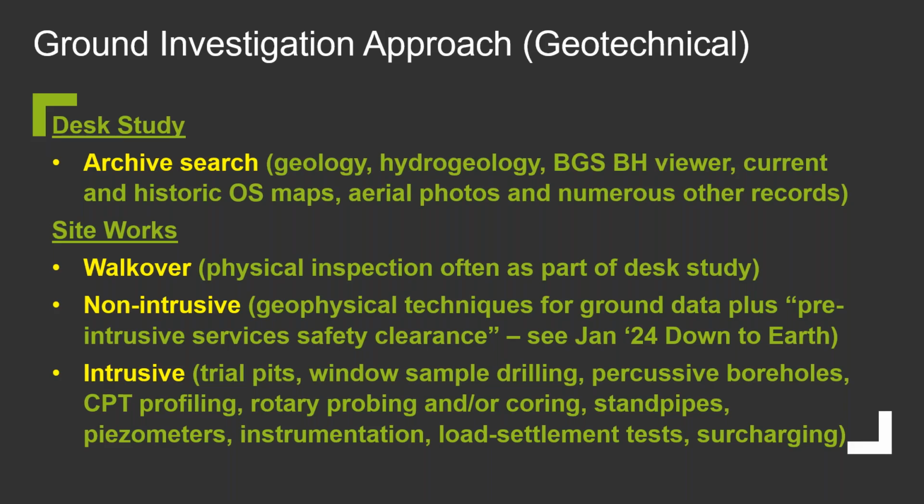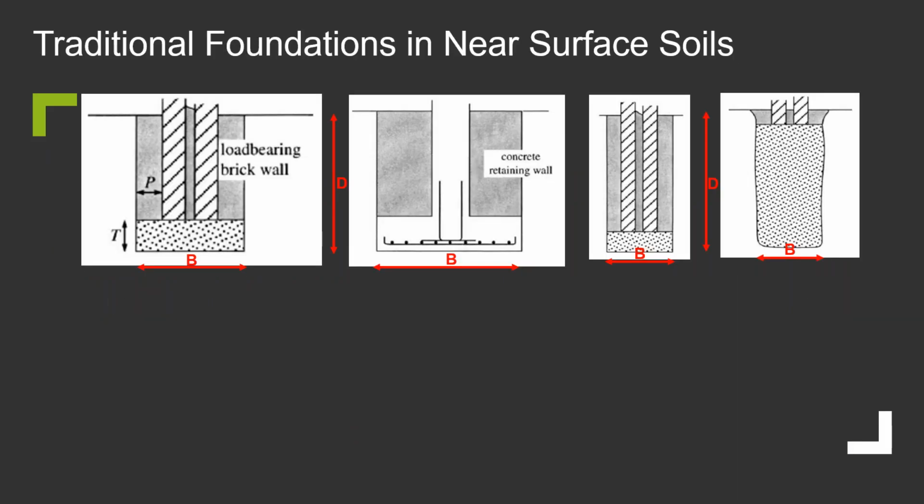whether you're looking at a site where the ground conditions lend themselves to ground improvement, or whether they are just looking at traditional foundation. That in mind, I suppose the cheapest situation on site for us would be we get to site, we do our investigation, we find competent materials within a very shallow depth so that we can use traditional foundations near to surface, and they're conceivably going to be the cheapest things that we're going to get away with. It's not necessarily get away with, but it's certainly if the ground conditions are adequate near to surface and we don't have, say, trees and desiccation issues with clays, then that shallow foundation may be absolutely fine